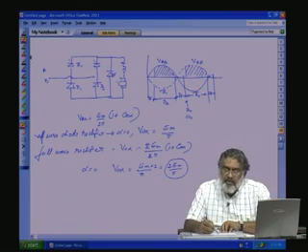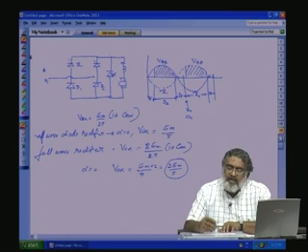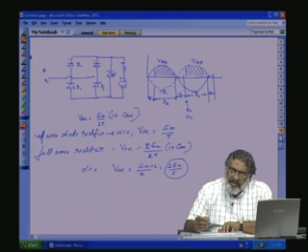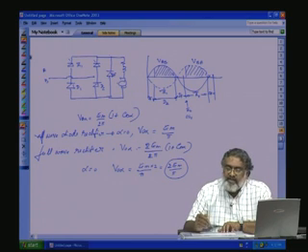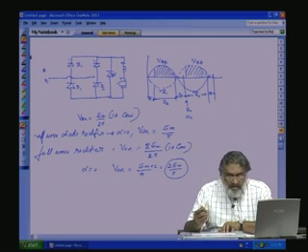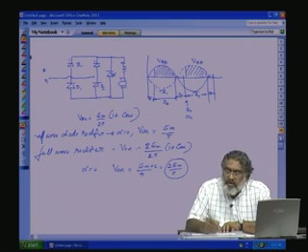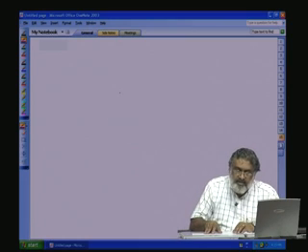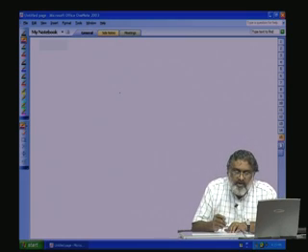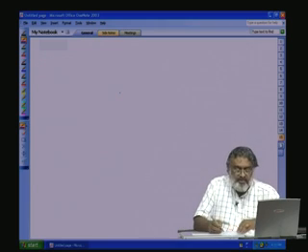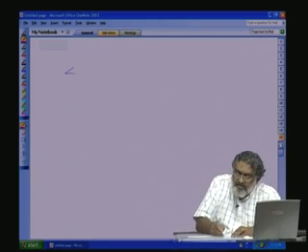Now, we have introduced the DF. This is another diode in the power circuit, that is another extra cost. Can we do away with this DF while at the same time ensuring correct freewheeling? So, let us think about another configuration to avoid DF. Let us go to the next page. This configuration is like this. See, we want to give a least resistance freewheeling path through the diode, not the thyristors. So, in that case, we can have this configuration.